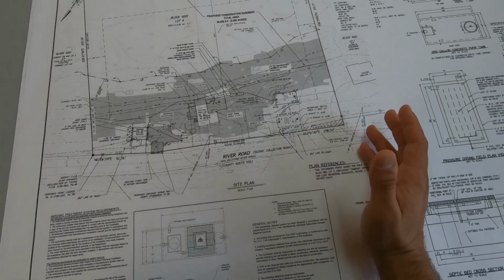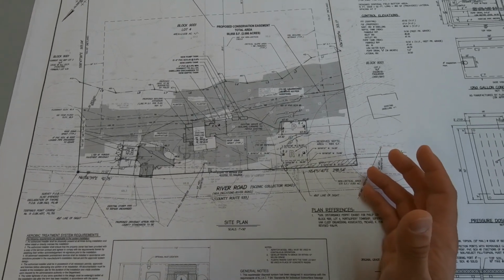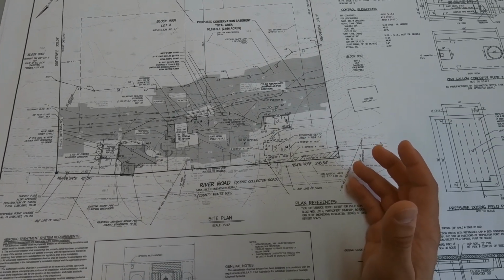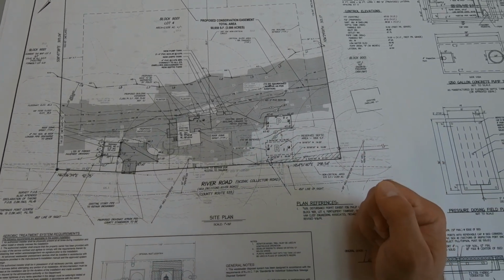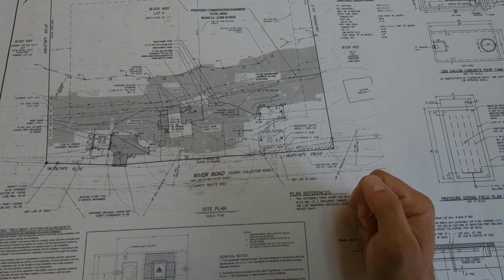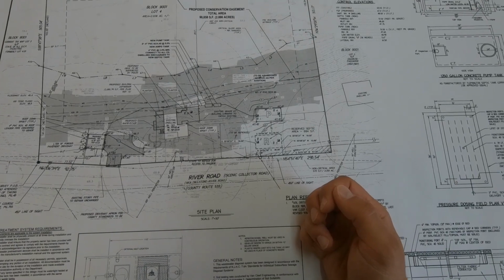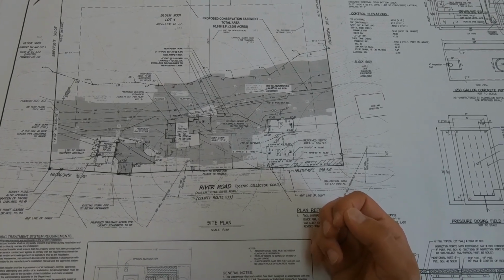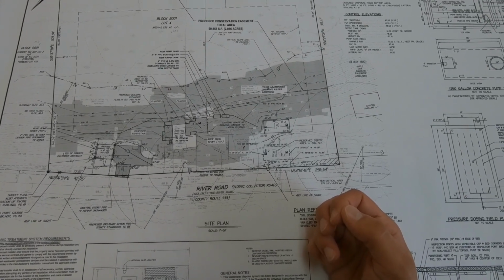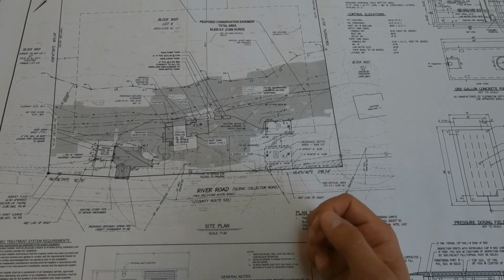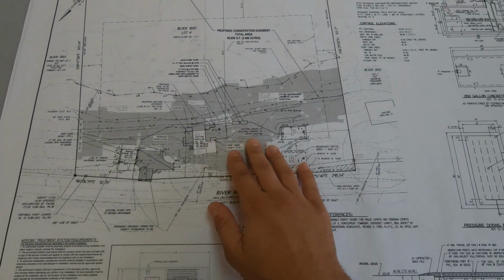Now, the stakeout sometimes is by our survey department, sometimes it's by the contractor or by somebody else, but it's just good to verify that the field is over 100 feet away from the well. You don't want treated effluent seeping into the well. That's a problem. So those are the major components.